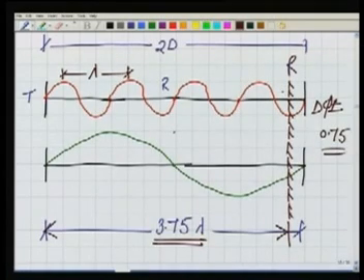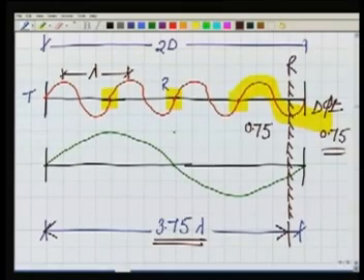As you can see here, the one wavelength is completed. If I highlight, this is where the first wavelength will be completed, the second one and the third one, and the rest for this particular part is leading to the measurement of the delta phi, the phase difference. So the phase difference, as in this case you can see, will be 0.75 in terms of the wavelength.